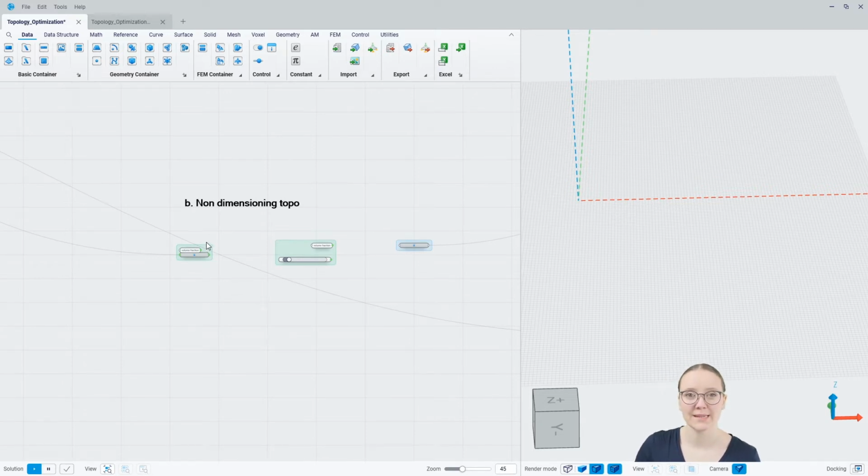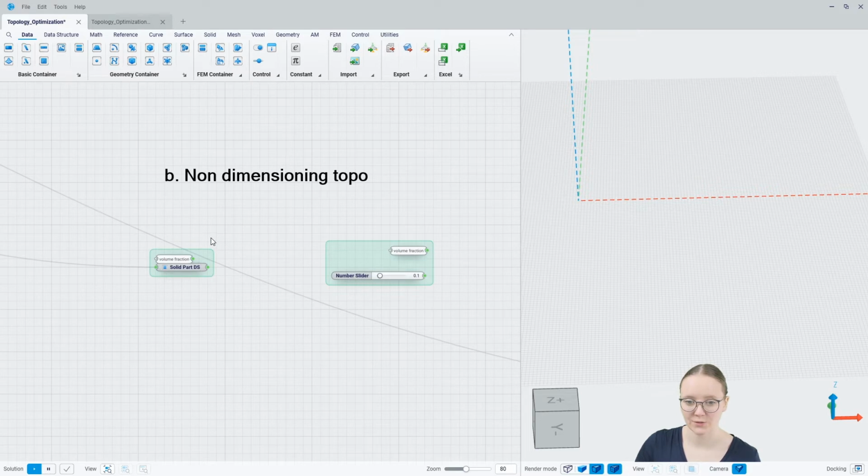This topology optimization is stiffness based using the volume fraction response, and you will get very discrete load paths. However, you will need further processing because these are not dimensioned yet. So this constraint is ideal for a reconstruction process using the skeleton process. If you define those discrete lines, you get a rod-shaped result, but then you have to do a cross-section optimization to actually get the ideal result for the stress.